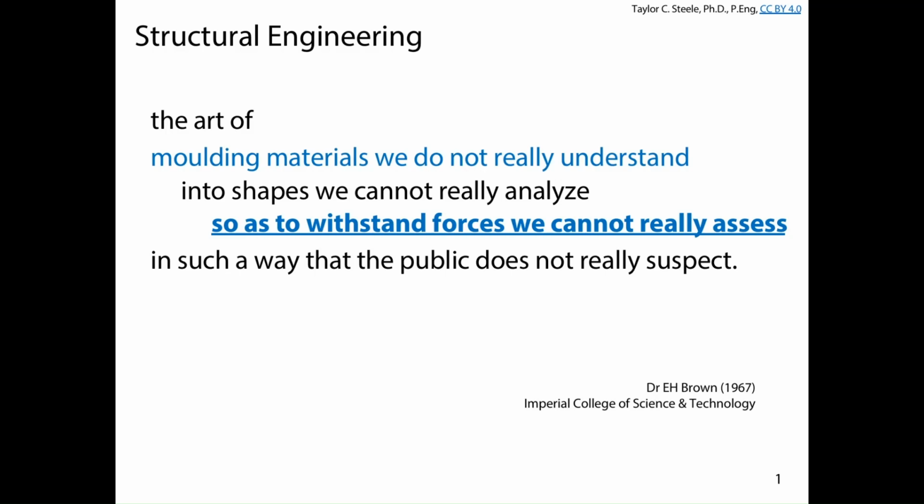In lecture 4, we talked a little bit about braced frames and bracing in structures and how lateral forces might act on a structure. Basically, we saw for a uniform pressure that might represent wind, we could treat the floors or the wall system that the wind is acting on as if it was sort of a floor system. We treated the floors as if they were joists and the braced frames more or less as if they were girders. Used the tributary width approach, some statics for a simple beam to get actions on our braced frames.